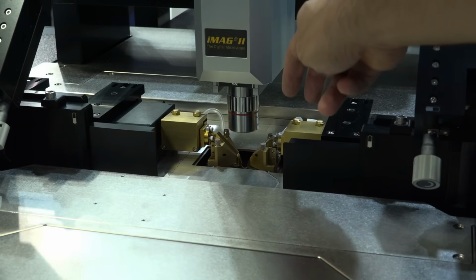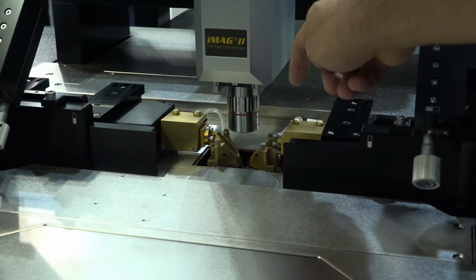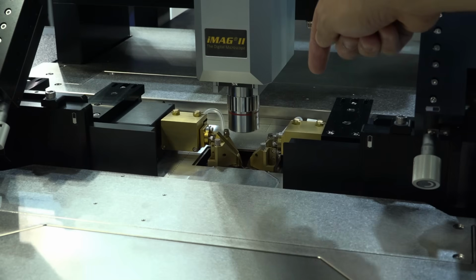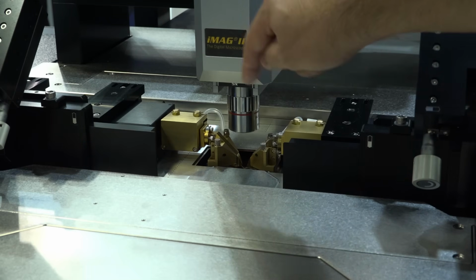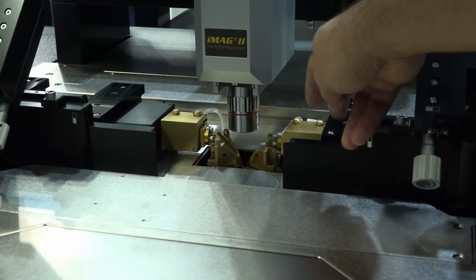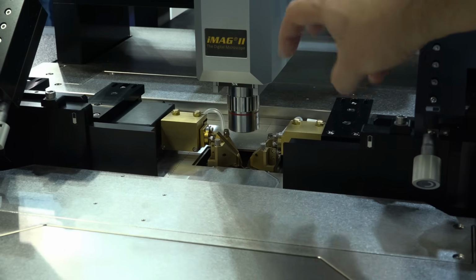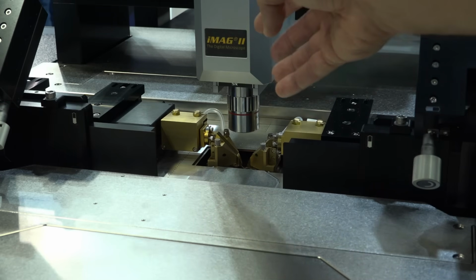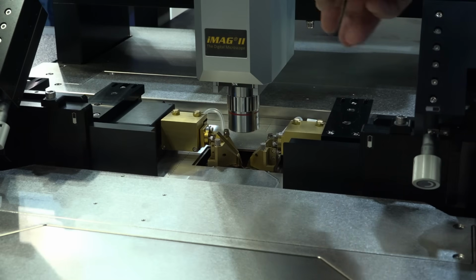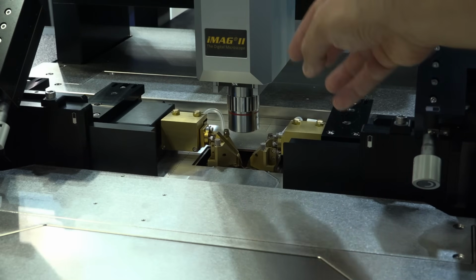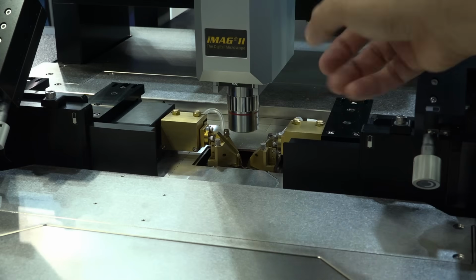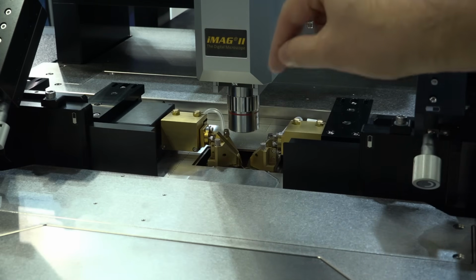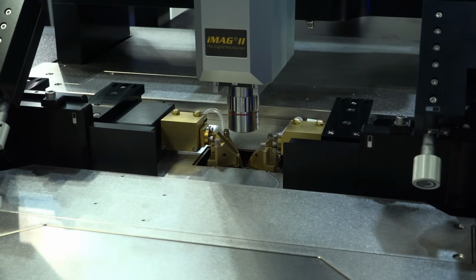So what they've done is that they have this kind of thermal guard in the middle where you have airflow going inside that cools the tip, as well as separating the actual probe from the terahertz module over here, completely thermally isolating them. That allows you to run this at any temperature, but not pull the temperature of the terahertz converter with your actual probe, which is huge, because once you calibrate and you heat up and cool down, you don't want your measurements to drift. So these subtle additions to the probe stations make them really unique for these kinds of measurements.